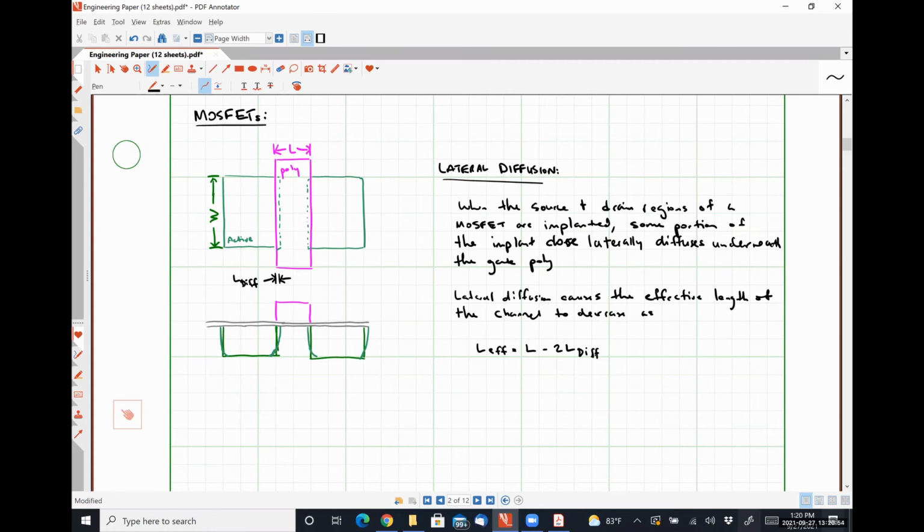So we are firing a beam of ions straight down over the entire surface of this wafer, and they are penetrating regions of the substrate, our P-type substrate on either side of our gate. Our gate should prevent anything from getting down underneath it because it's a physical impediment to that happening.